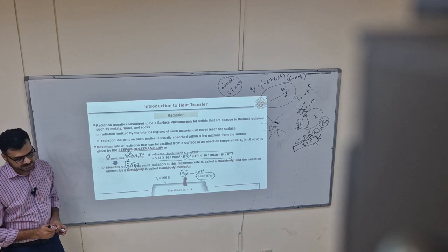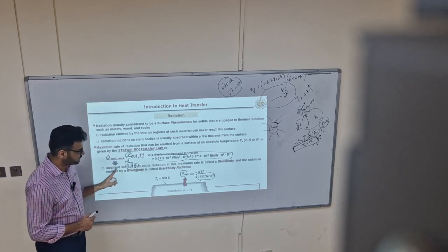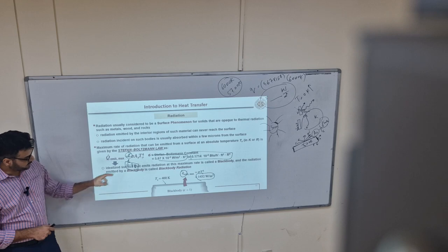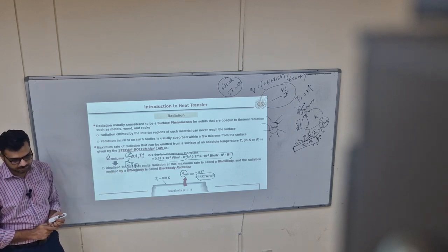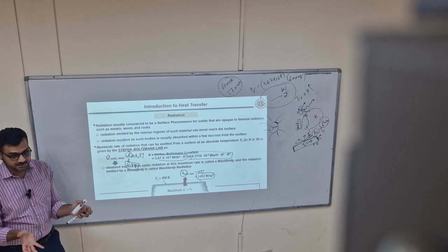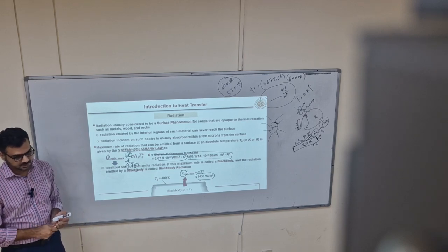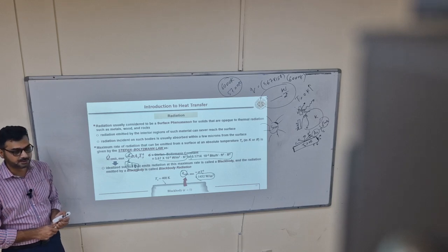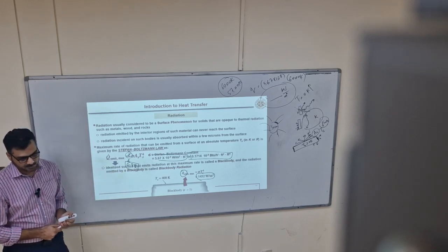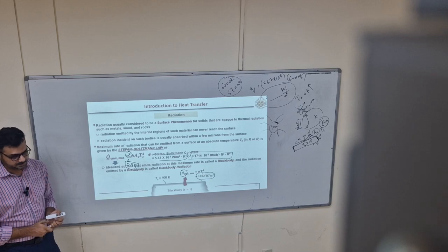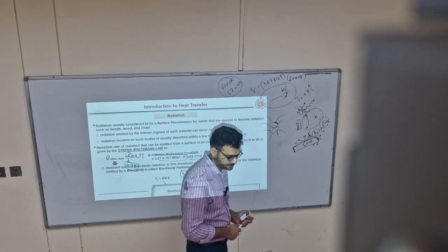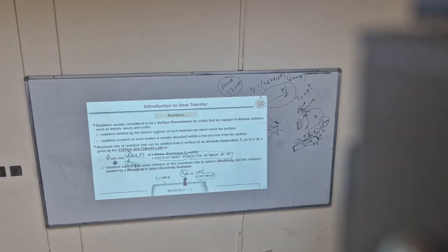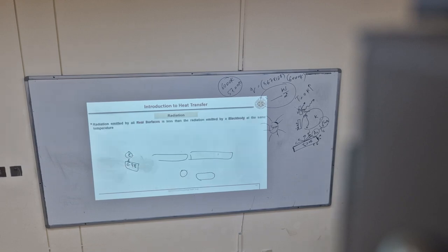That is emittance. Then we will learn another thing, absorptance. Black paint has this maximum, but there are other materials, artificially made substances, which do not look black but have very high emittance or absorptance. Also, human skin is more than 90%. Our skin is not even black, even then its emission is more than 90%. Okay, so let's move on.